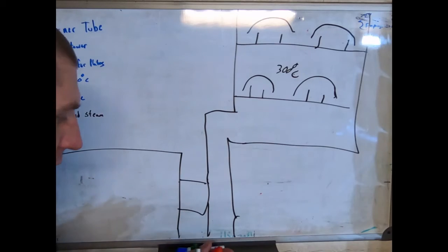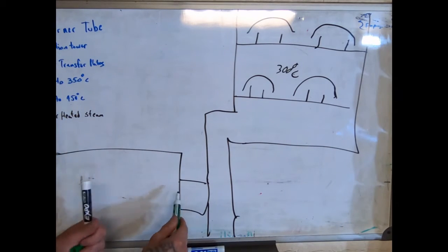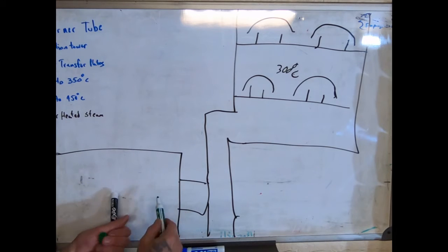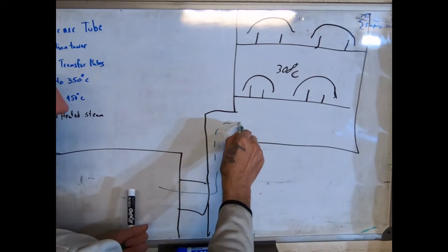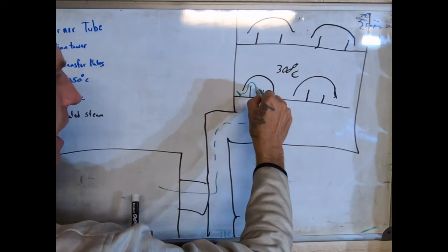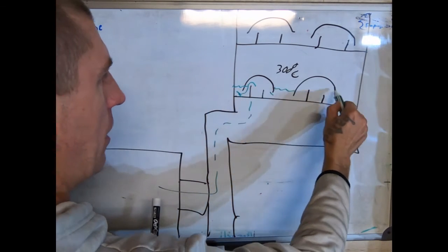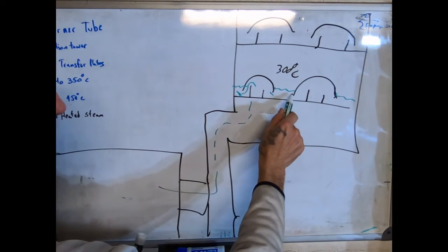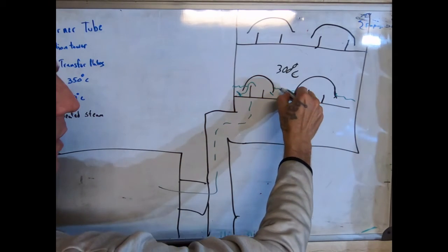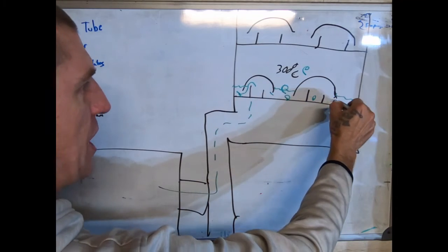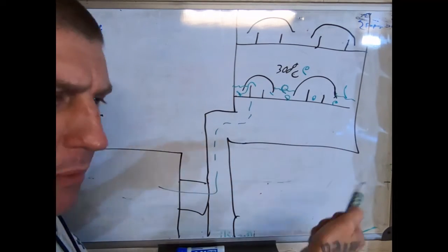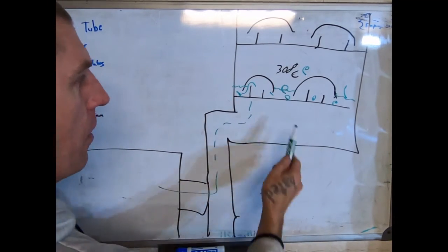So in this first layer, the gases coming out of this pyrolyzer here would come up, vent out, and turn into a liquid in this first area. And that liquid would go just beyond the top of these, and the rest of the gas would bubble out of this region. And that is why this is called a bubble cup fractional distillation tower.